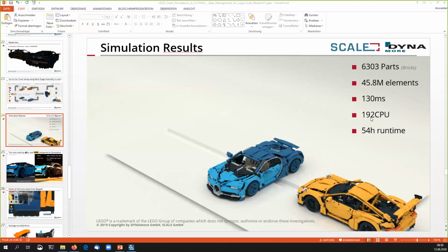The president asked before, and I didn't understand whether it was the MPP or SMP code of LS-DYNA. SMP is not parallel. MPP is multiprocessor parallel. And do you know which LS-DYNA code was used in this calculation, MPP or SMP? It was MPP. MPP, okay. And we had to use double precision.